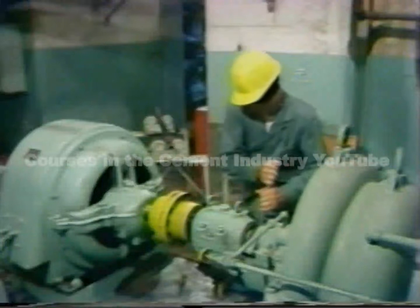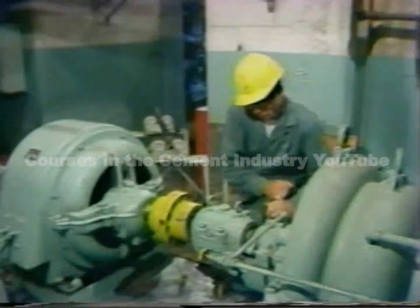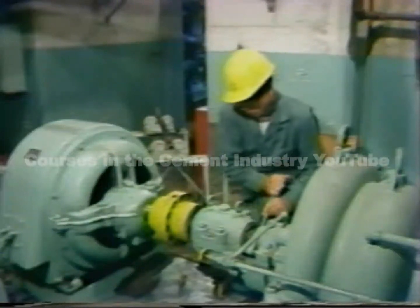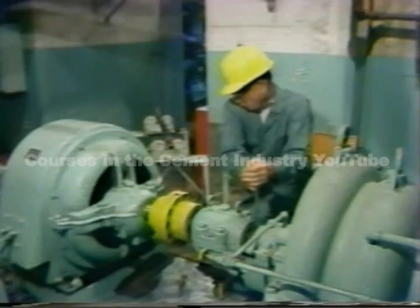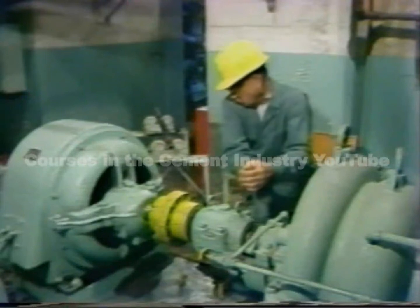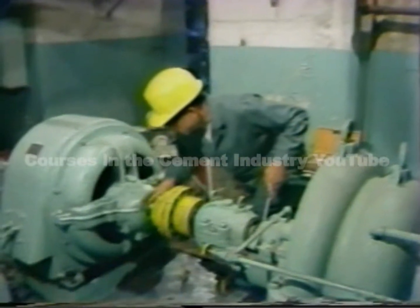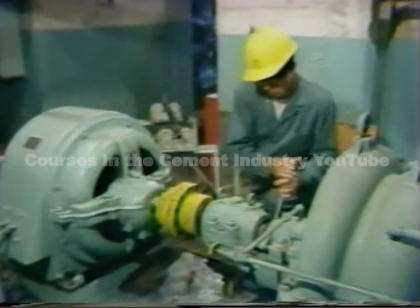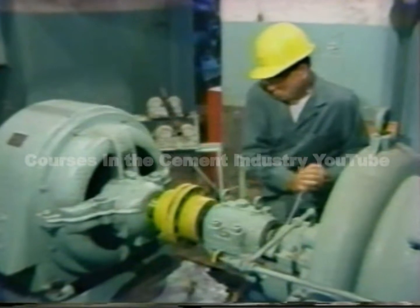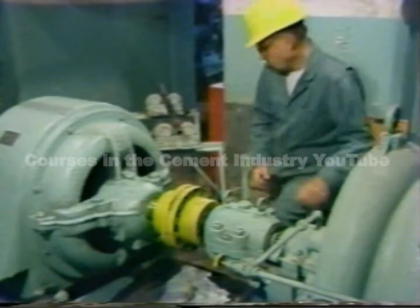Before you can select the equipment you'll be using, you should rotate the shaft and inspect it to determine the best place to mount the post and bracket. Once you know where they're going to be mounted, you can determine what size rod to use. When you're rotating it, check for keyways or any other obstructions that may limit the point where you can mount the post and bracket. Remember, we have to mount one on each shaft to span the coupling.